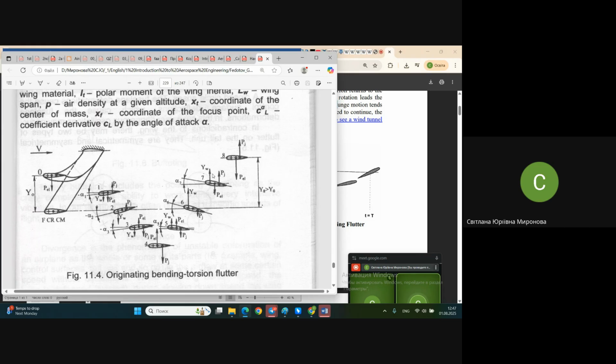And what happened? Look, Flutter may happen. It's self-oscillating and self-supporting, let's say. It's not caused by permanent input of some additional energy. Once started, it continues until conditions for this Flutter disappear. And it's necessary to understand what these conditions are.